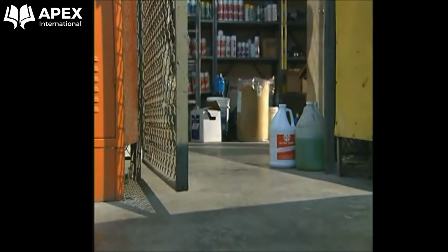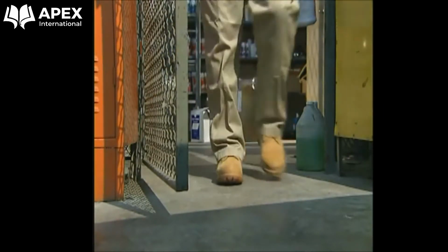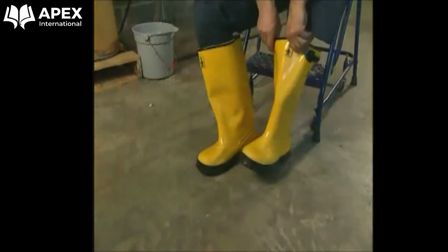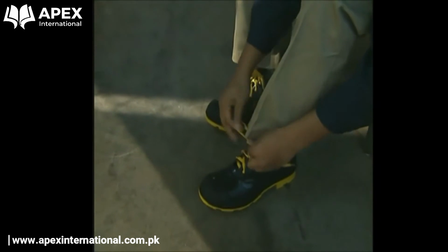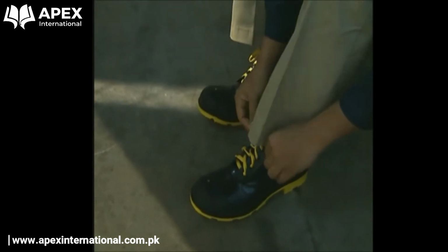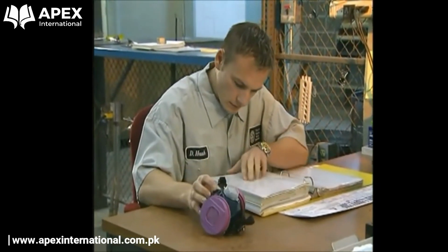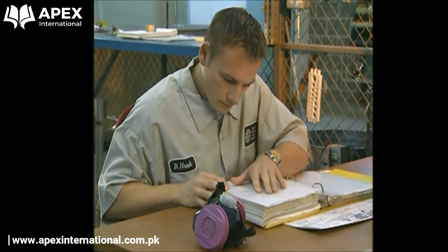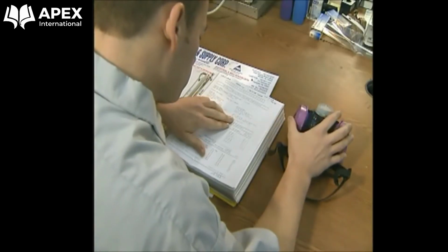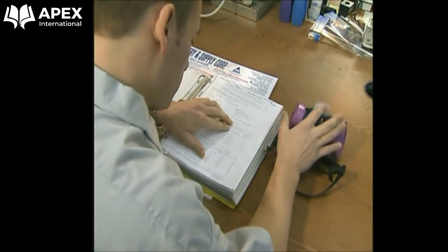Your ordinary safety shoes may not protect you against all chemicals, corrosives, for example. Wear rubber boots, rubber overshoes, or synthetic rubber and acid-resistant work shoes to be safe. Check the MSDS to ensure you are using the correct combination of personal protective equipment for your situation. Your employer will provide the appropriate PPE, but it's up to you to use it properly.